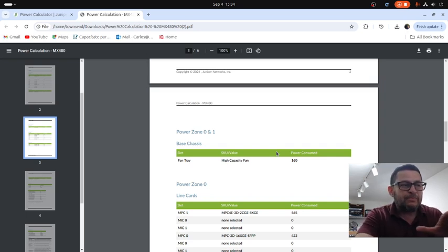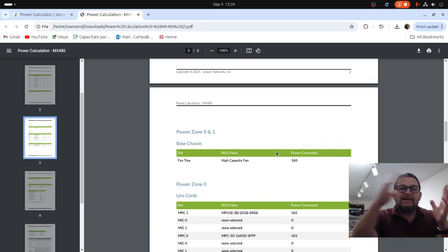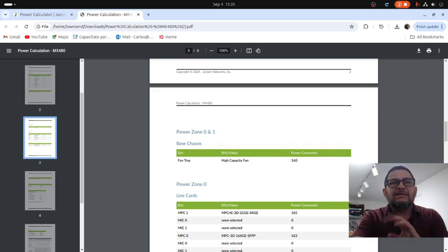We have 4 power supplies on that. Basically 2 power supplies work together, PEM 0, PEM 1, PEM 2, and PEM 3, and 2 of them can cover the total watt capacity. But the thing is, the other couple of power supplies work as redundant power. In case one power supply fails, they can compensate for the amount of power demanded by the chassis and all components. So let me connect the chassis, guys.